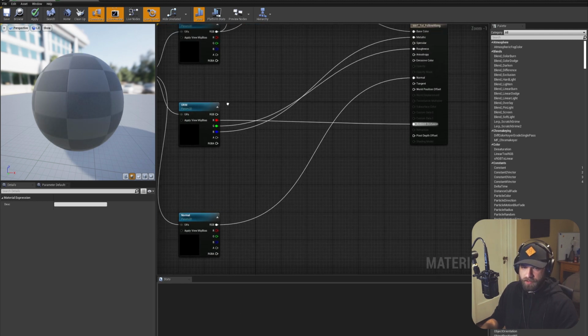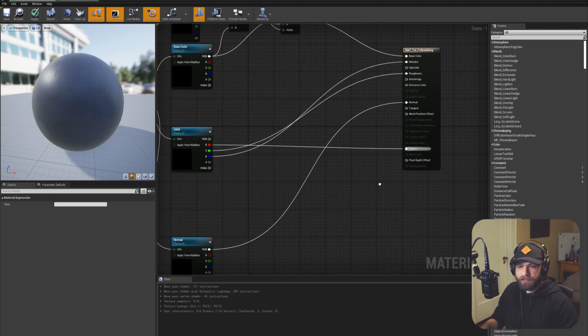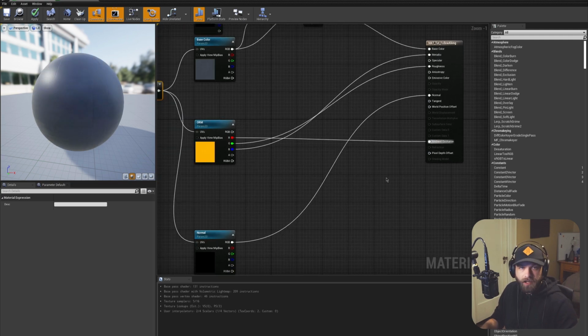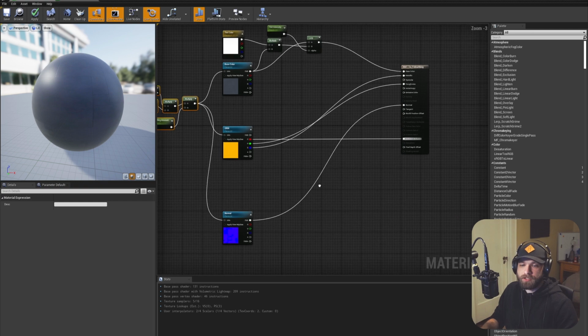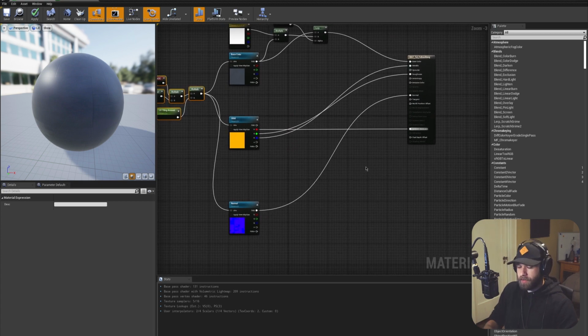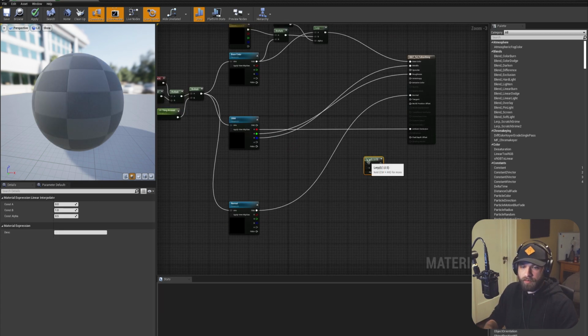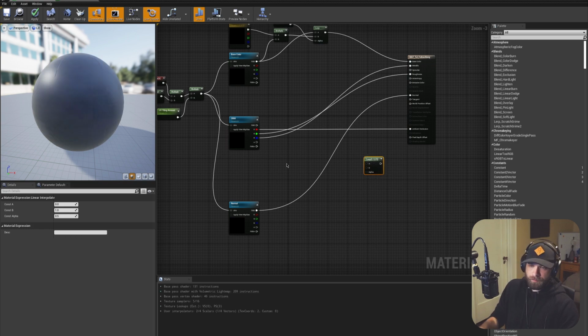And we'll go ahead and start with the ambient occlusion here just because it's in the red channel and it's at the top. There's actually not much to do with the ambient occlusion for this basic material. We're just going to basically give the ability to control the intensity of that ambient occlusion in your map. And to do that, we're going to go ahead and create a lerp, which again is going to, if you hold down L and click, it'll create a lerp node.